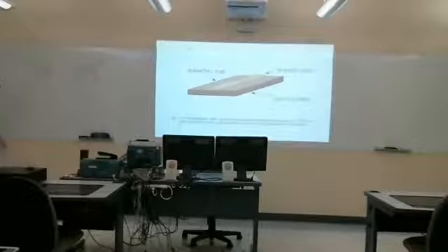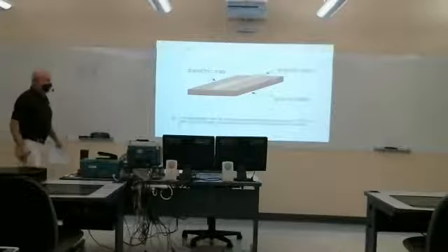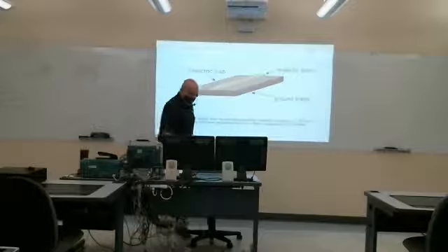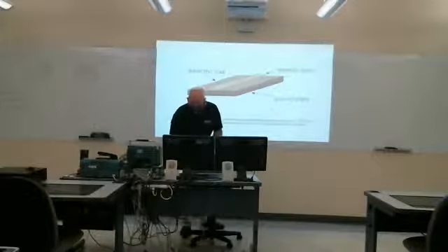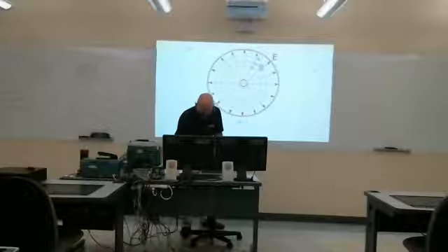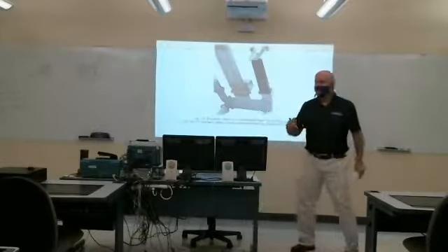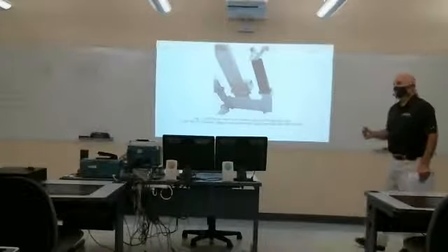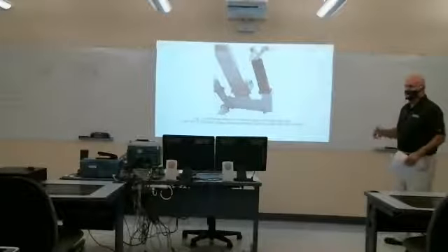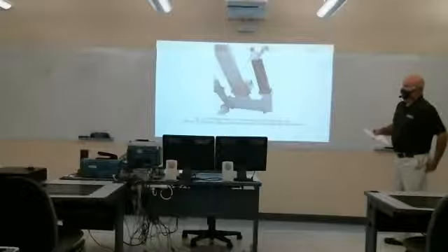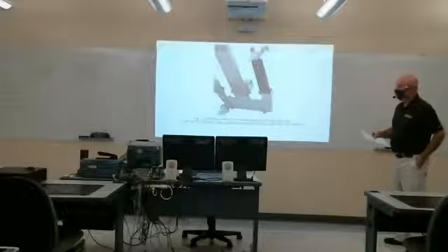And again, we will typically use the term transmission line when we're talking about this particular mode of propagation of the wave where the electric and magnetic fields are transverse to the direction of propagation. At higher frequencies, you run into more complex modes of propagation where the wavelengths are very short, and you run into what are known as transverse electric and transverse magnetic modes of propagation.